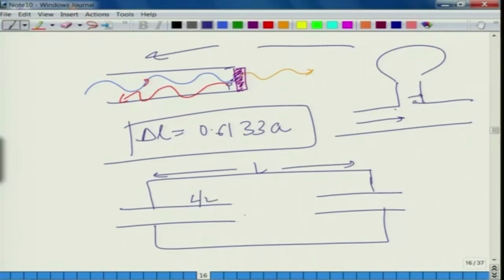The impedance or the resonance frequency of this quarter wave resonator would effectively cancel out the trough or the first axial resonance of this chamber. We will do all the maths later, but the point I am trying to make here is that you carefully analyze this small pipe, and you have a big chamber, something like a pipe which is being extended into a big muffler cavity.